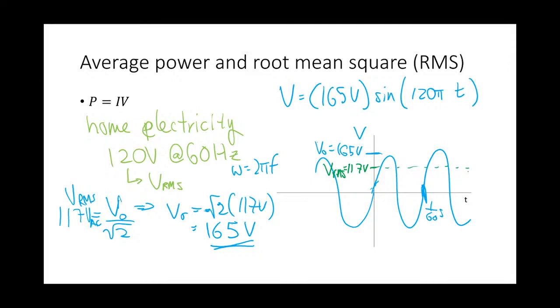But if you dig into the details a little bit more, the amplitude is a little different from the RMS value. And then sometimes, instead of quoting these two numbers, confusingly, we quote another number, which goes from peak to peak, quoted as VPP.